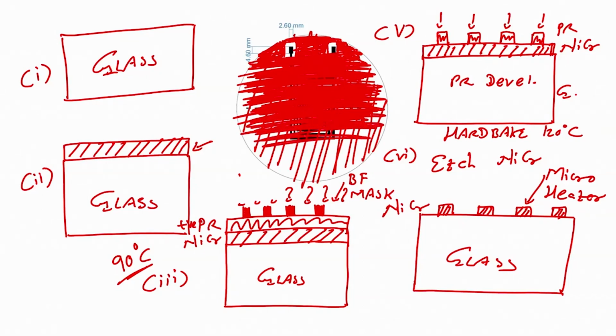using PECVD, plasma enhanced chemical vapor deposition, right. What you can see, only the contact pads of the heater are free of silicon dioxide. So, once you deposit or grow silicon dioxide and perform photolithography such that the silicon dioxide is etched from the contact pad, the next step would be to fabricate interdigitated electrodes.